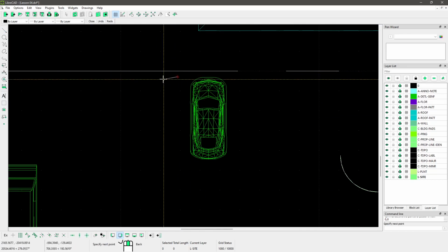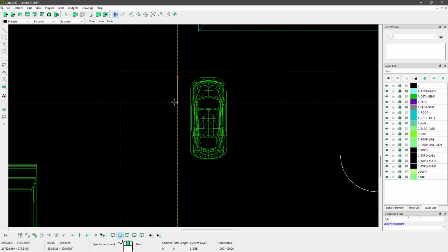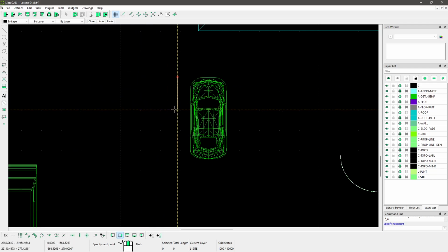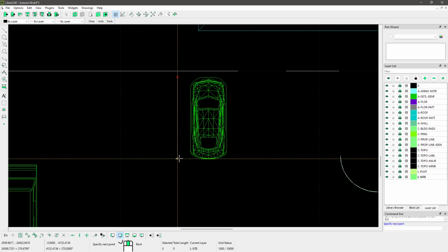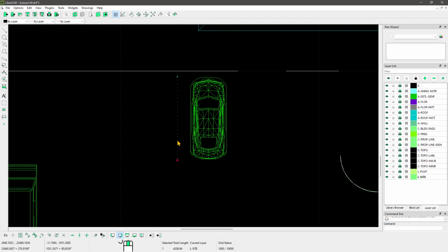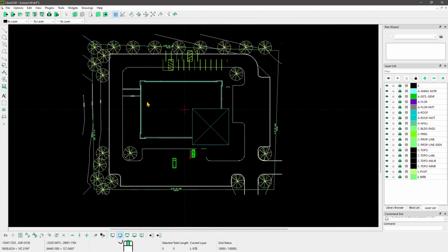So I can click once, and if I hold the shift key, you can see that I can draw more precisely, perfectly vertical, perfectly horizontal, and then with a degree interval. So I'm just gonna click first there and then second point right here and press ESC. Then I will select the line, go here, and you can see that now I am at 4,000 millimeters. So if I see now, this is millimeters, this is good. It's not wrong as previous. So I don't need to scale. I don't need to resize this as the previous example.